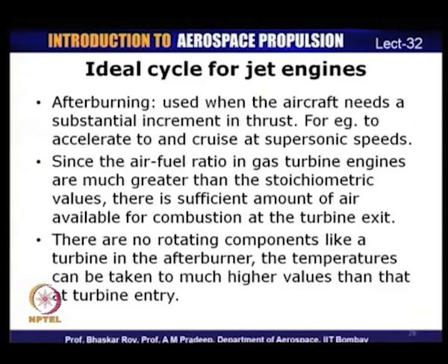What basically happens is that afterburning is primarily used if an aircraft needs to have substantial increment in thrust, like if it has to accelerate and cruise at supersonic speeds, and since the turbine exhaust has sufficient amount of air that is available for carrying out combustion. And the third point is that in an afterburner there are no limits to temperature like in turbine entry, because there are no rotating components present in an afterburner. So, you can have higher temperatures than what is permitted for turbine entry.